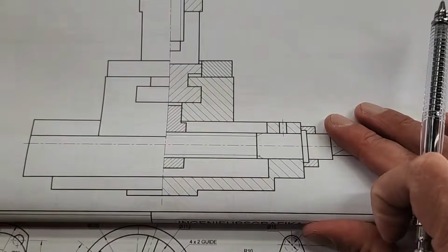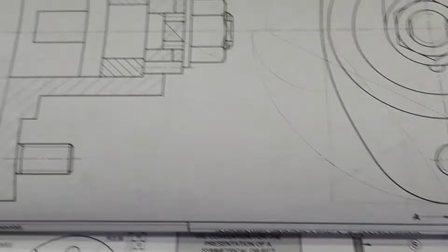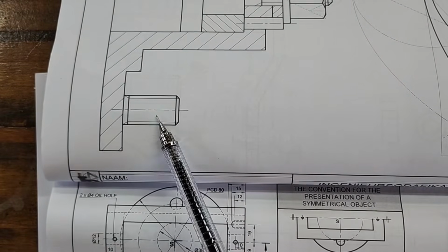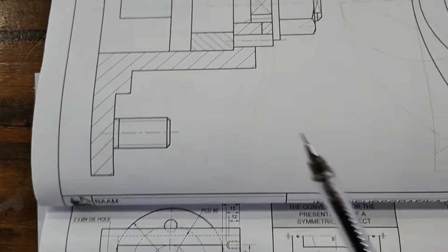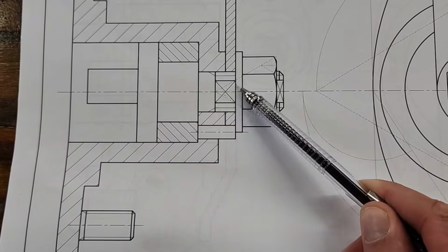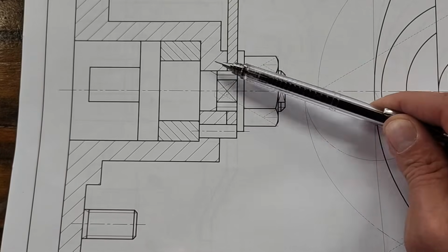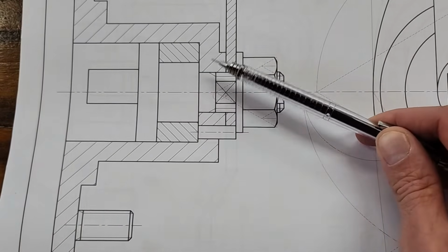All right, let me see. There's one more thing here. All right, there's a stub also, it's a part of a fastener, so there is no hatching there. Square on a shaft again, you'll see hatching, washers not, nuts not. There's a handle here, adjacent components, different direction.